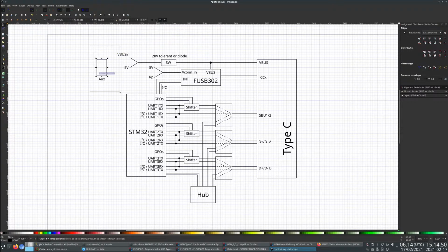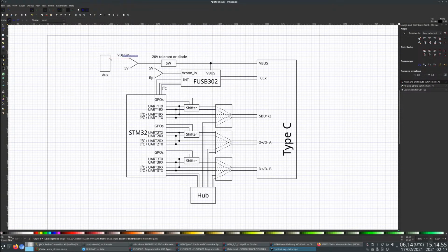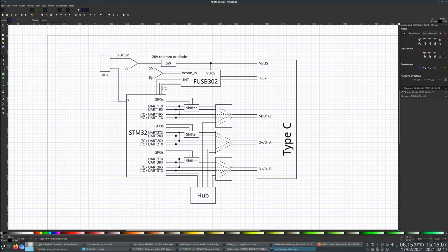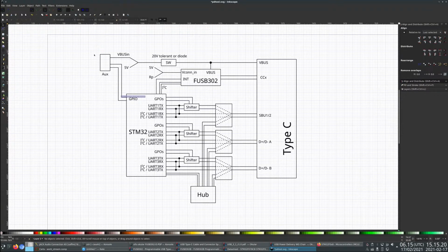And so you can say this is basically for if you want to emulate a USB power supply. We can have an AUX connector, and then that will also have some kind of, probably I2C or just GPIOs or something. It probably won't be the internal I2C, but this is definitely fine to do bit banging anyway. At least two GPIOs, for if you have an external power supply, something you can plug in here to control it.